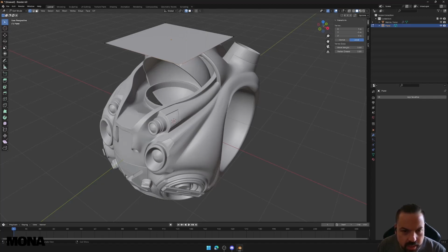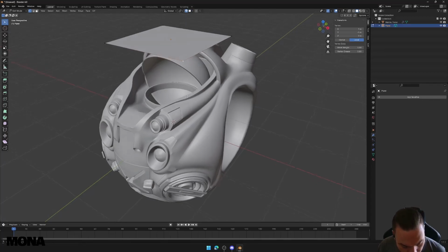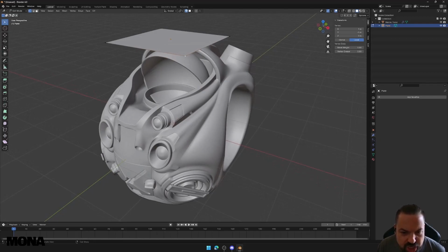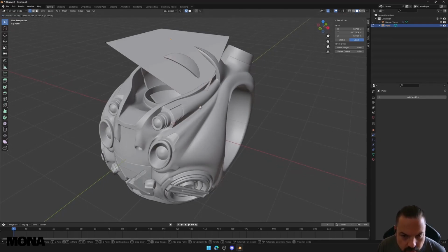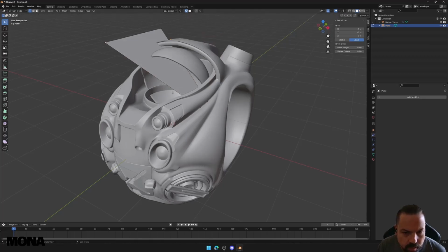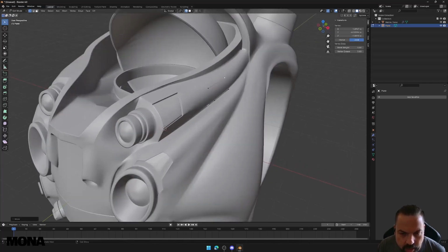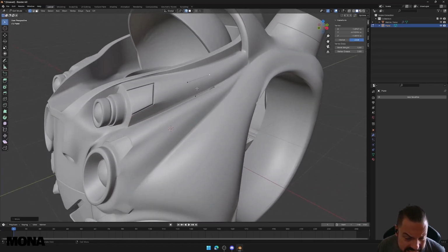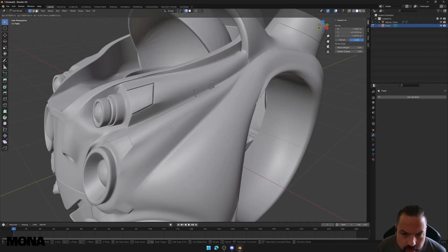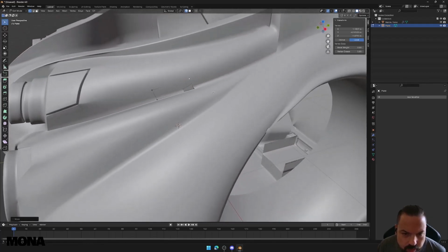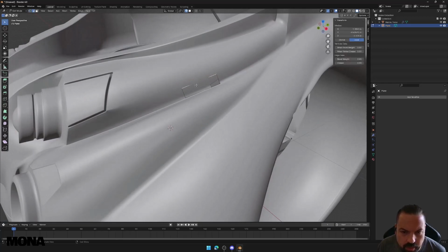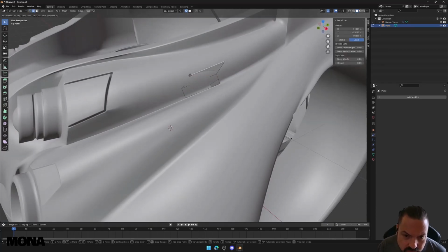And once you get a polygon there, no, a vertex, and you press G, it's going to snap to the asset, right? And that's basically it. So say, for example, I could sort of do that. And then I'm going to grab that and go E.